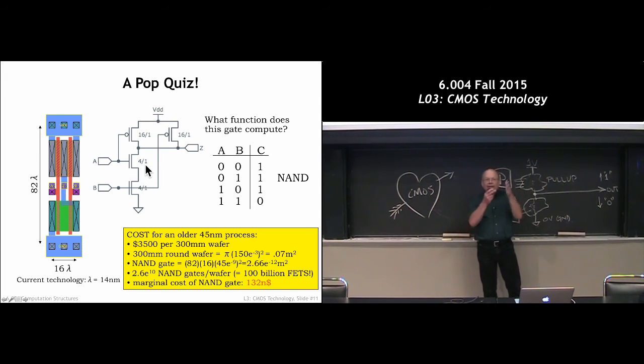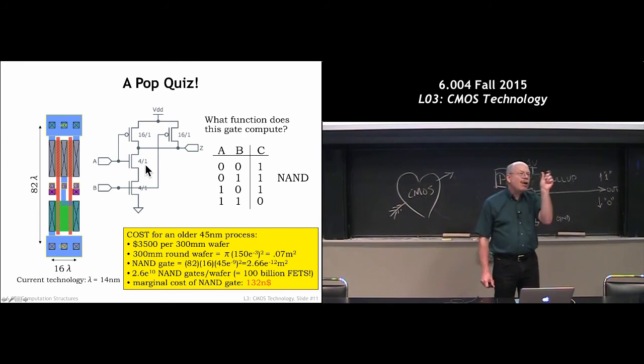They're big schematics, but little devices. Cute little stuff. So this logic gate here in a modern process will produce its answer in a few picoseconds. A few picoseconds after you put in the input. So how long is a picosecond? Okay, how long does it take light to travel this distance in picoseconds? It takes 1,000 picoseconds for light to travel this distance, nanosecond a foot. Right? So we're talking a very, very short period of time.